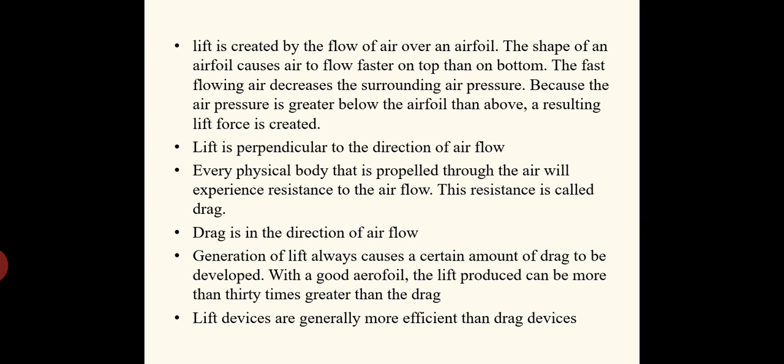See, it is just utilizing the velocity of the wind to produce the rotation. That's all. There are no aerofoil shapes and nothing there. What we are doing is providing a resistance to the flow of the fluid. Due to that resistance, the fluid will exert some force on the body which is placed in the flow. So that is being thrown back. That is what is happening. Since it is connected to a rotor, continuous rotation is produced. So that is the basic working of the wind turbine or windmill based on the drag principle.